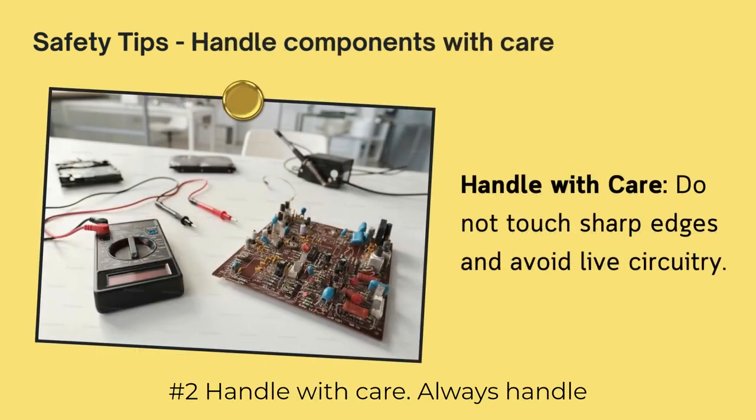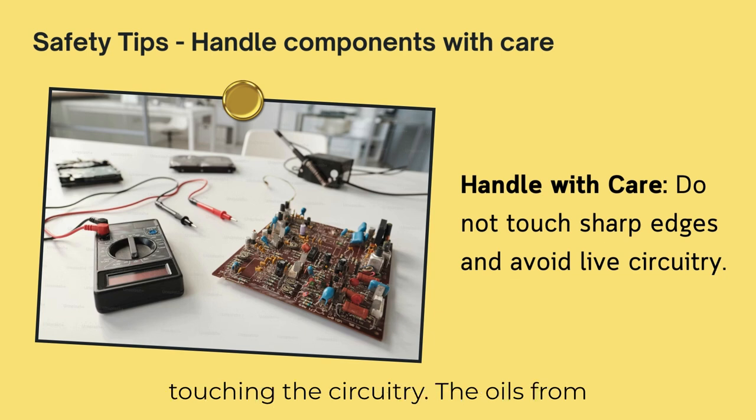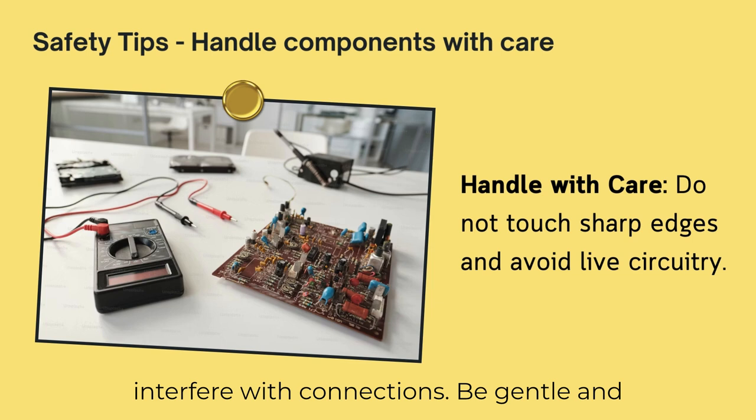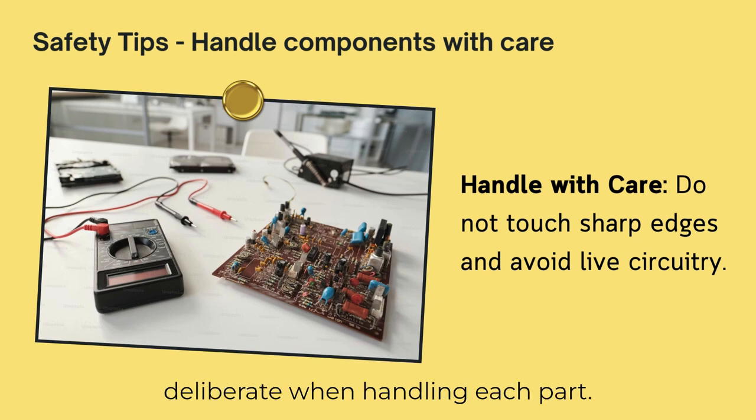Number 2. Handle with care. Always handle components by their edges and avoid touching the circuitry. The oils from your fingers can cause damage or interfere with connections. Be gentle and deliberate when handling each part.